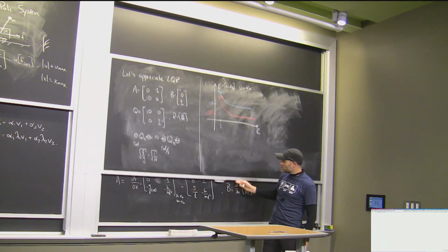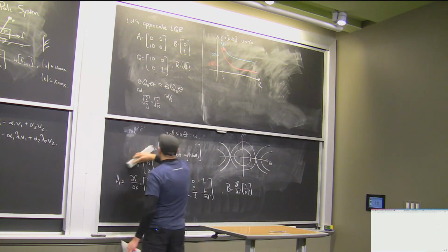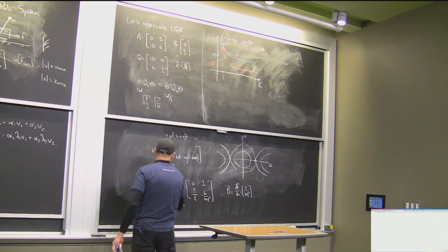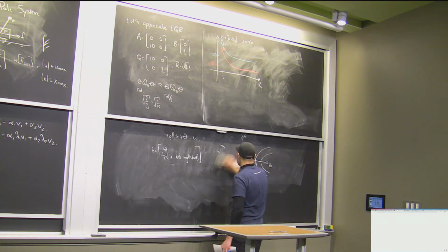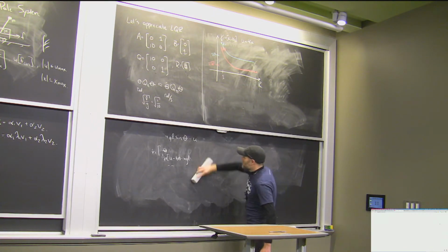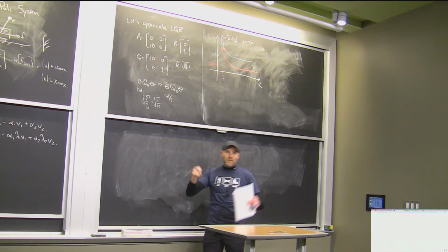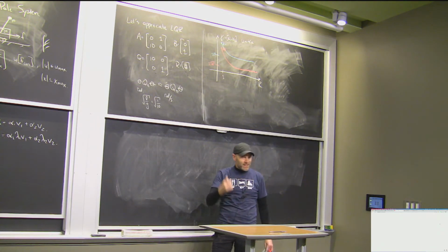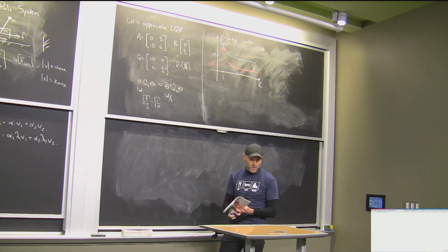I can make that point quickly. If you ever tuned up a PD controller, and you made K1 bigger and then K2 bigger and then something went bad and something went good, it's non-trivial actually to find the balance between K1 and K2 and to get good performance.